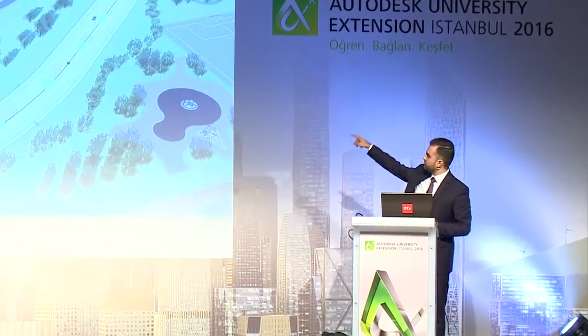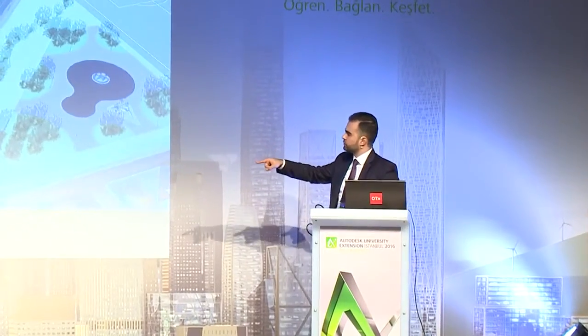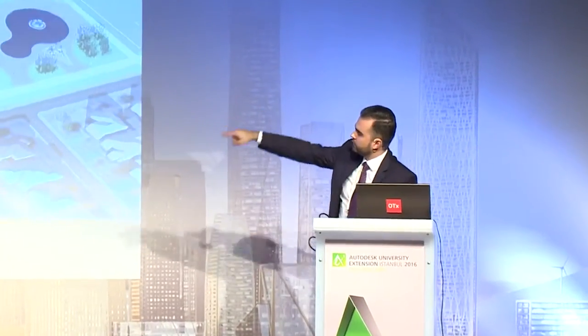Okay, this is just an example of InfraWorks. So I'm laying a certain road, a highway, for example, a 2-lane highway, and I'm opening it in Civil 3D. You will see that it will open instantaneously. I just have to select the area of interest, open the InfraWorks model. I'll be able to pick what data I want to import. Here we've got the terrain, for example. If we have watersheds, we have the alignment of the road.